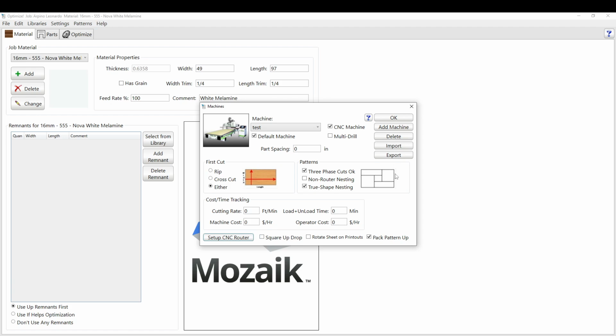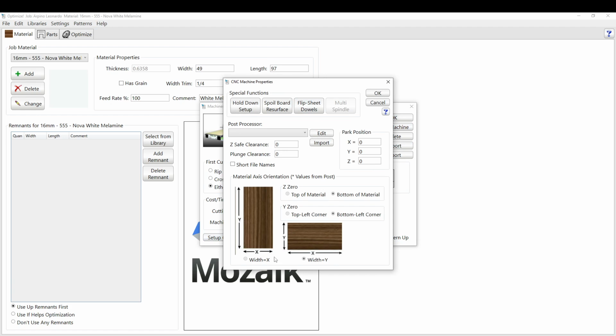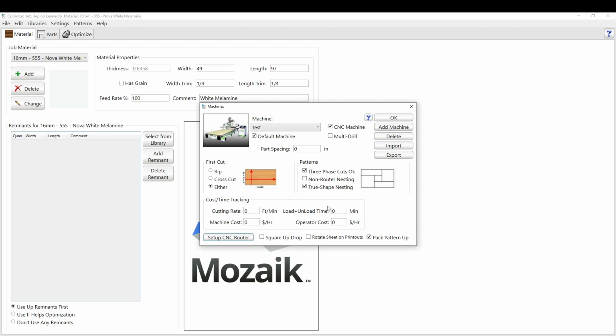Okay, so you basically have set up your CNC. That's how you set up the machine. Make sure you have this post processor and it's correct. Do a test run with a thing before you actually start trusting it. And even at the beginning, don't trust it right away. Give it 3-4 months before you really feel confident in it, because there's always bugs and stuff that you should keep an eye out for.